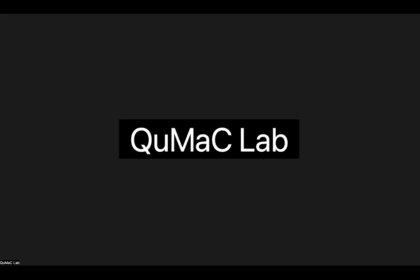Because when you multiply LO and RF, only when you do sine with sine do you get the sine square term. Right? When you do sine and cos, then when you low pass filter it, that sine and cos alternately become positive and negative, so they cancel each other out. So that's why only one of the terms shows up here and the other one shows up there. The IQ mixers can be used in this form as well in the demodulation part.